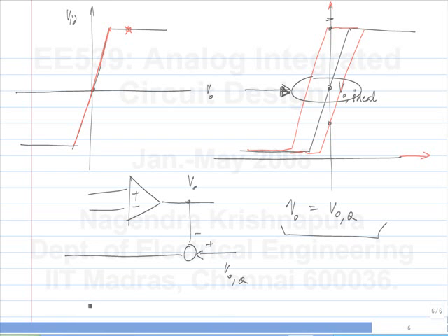When we started off with a negative feedback amplifier, we said we'll integrate the difference and then feed it back. Now, we already have an op-amp which does the integration, so we don't have to make another amplifier just for biasing. We just have to provide something proportional to this difference to the inputs.